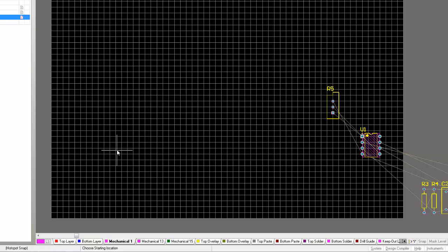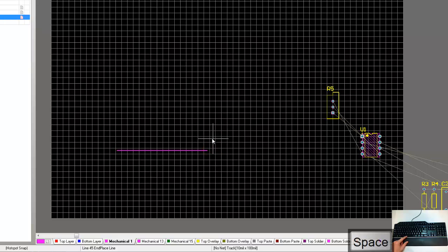and this is incorrect. Starting at any point on the PCB document, click once and a pink line will start to be drawn in either the X or the Y plane. Clicking a second time will fix the line, creating a waypoint. The line will then try to angle away from this point at 45 degrees. If a 90-degree angle is required, pressing spacebar on the keyboard will facilitate this.